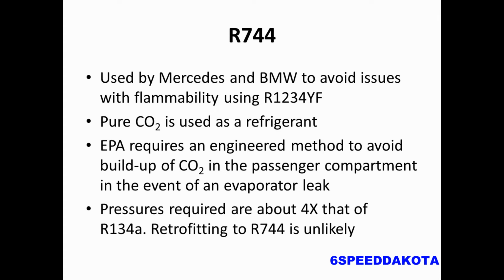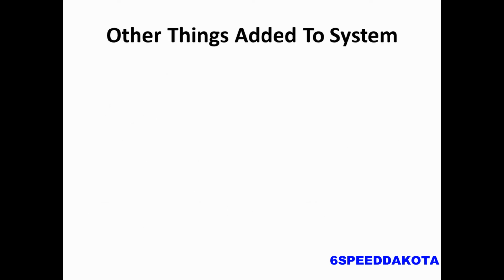So pressures being about 4 times that of an R134A system makes retrofitting to R744 expensive and very unlikely.